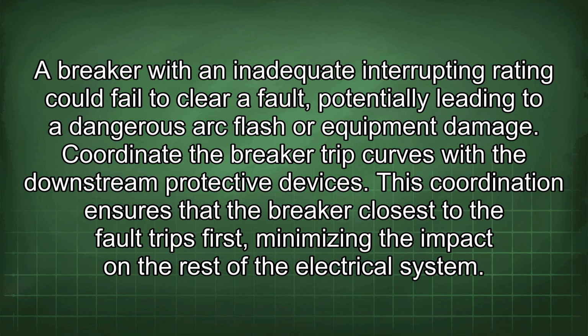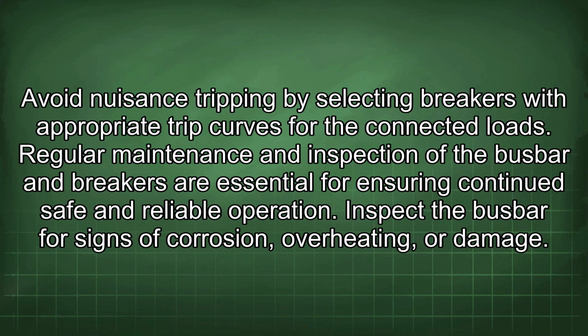Coordinate the breaker trip curves with the downstream protective devices. This coordination ensures that the breaker closest to the fault trips first, minimizing the impact on the rest of the electrical system. Avoid nuisance tripping by selecting breakers with appropriate trip curves for the connected loads.